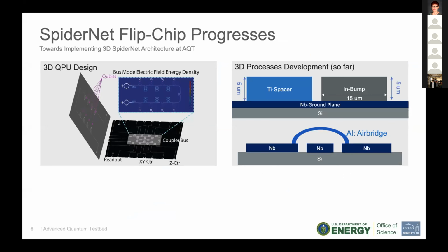It's this coupler bus. It's basically a multi-mode meander resonator. And we are going to use its 8th order mode to mediate the coupling between all the 8 qubits. One particularly important element attached to the bus is that there are 2 square loops at the ends of the bus. We're going to use it to dynamically change the boundary impedance so that we can modulate the bus on the fly, as I'll mention later.